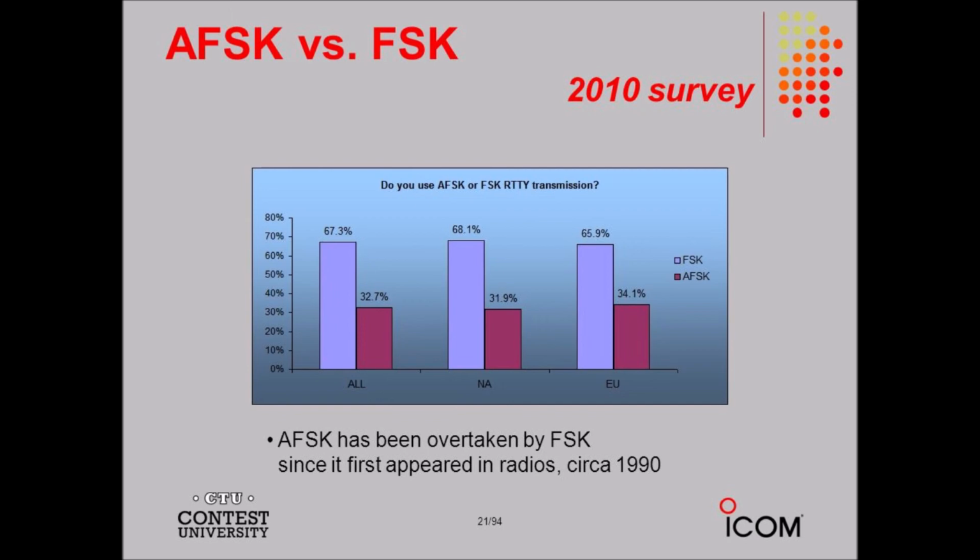Deviation for FM and PM. In an FM or PM signal, we can quantify the maximum extent to which the instantaneous carrier frequency differs from the unmodulated carrier frequency in terms of a parameter called deviation. For most FM and PM voice transmitters, the deviation is standardized at plus or minus 5 kHz.